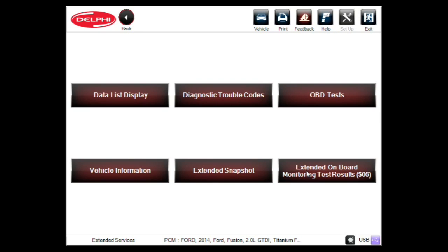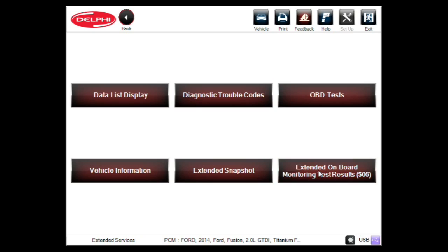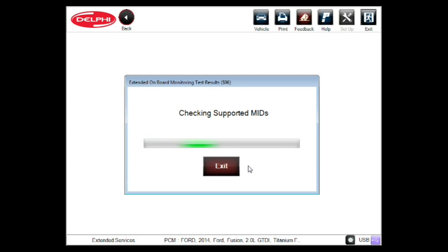We're in enhanced powertrain. Now we can also see mode 6 in generic powertrain, but we'll usually see the defined parameters, not always, but usually, if we're going to find them, we'll find them in enhanced. So we're in mode 6 in enhanced powertrain. Let's go and see what the categories are. They're going to be a little different than what you've seen with pre-CAN bus vehicles.